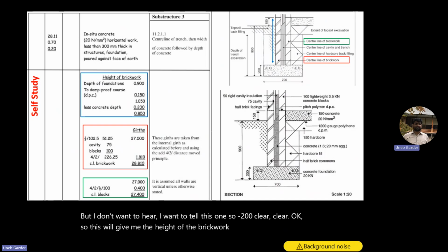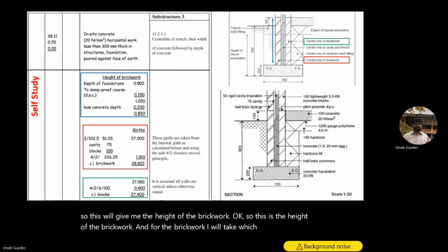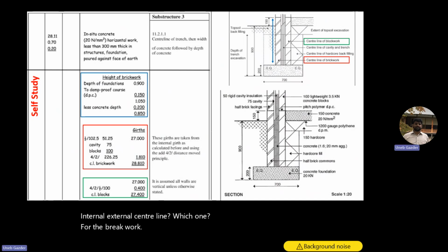Okay. So this is the height of the brickwork, and for the brickwork, I will take which length? Internal, external, center line, which one? For the brickwork. Center line. Okay. Anything related to the wall? Center line.